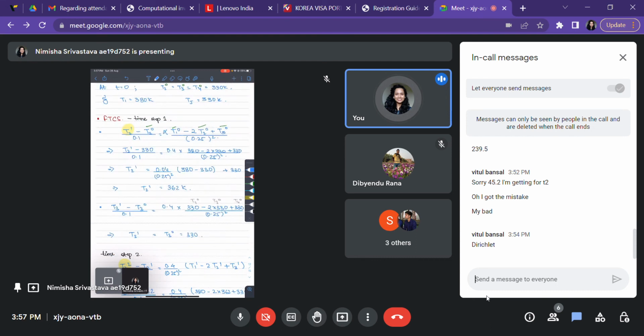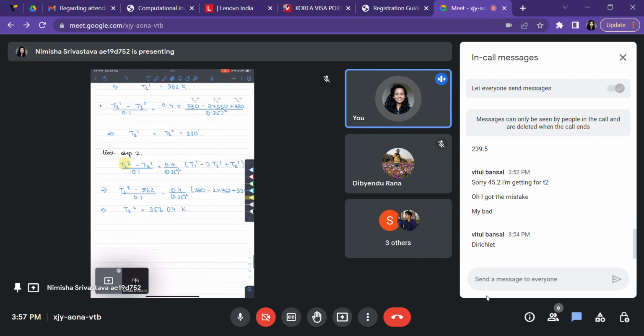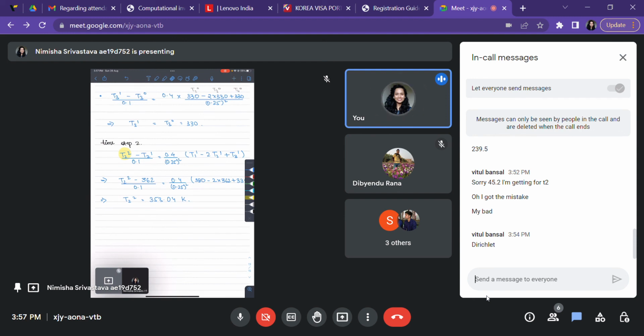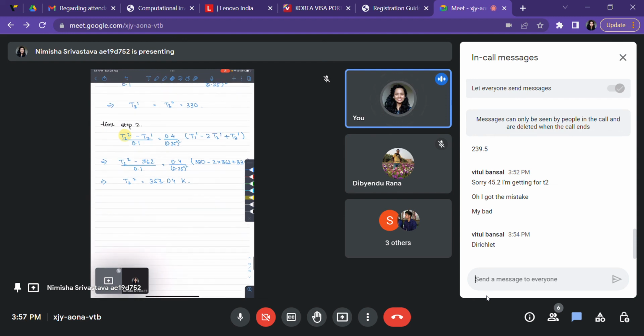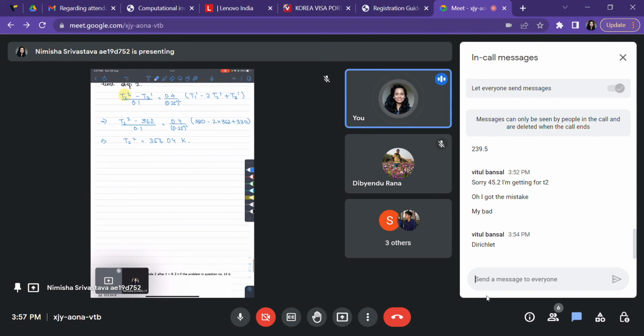One important aspect is that you have to keep on marching in the neighbors as well. Since I'm looking at node 2, I need to know the values for node 3 as well as node 1 at each of the time steps as I keep on moving, because those are the values that I'm using in my computations. Okay, so I hope that's clear. Okay, we'll move on.